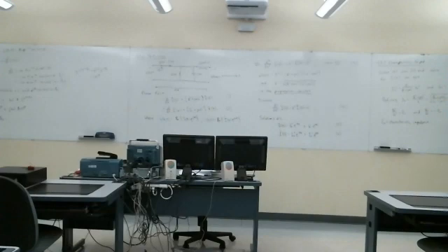R prime plus j omega L prime, well, this is going to be 0.164 plus j omega L prime, here 200 pi times 10 to the 6 times L prime, that's 370 times 10 to the minus 9, or 0.37 times 10 to the minus 6. So you're going to get 0.37 times 200 pi. That becomes j 232.5 when you do that calculation.